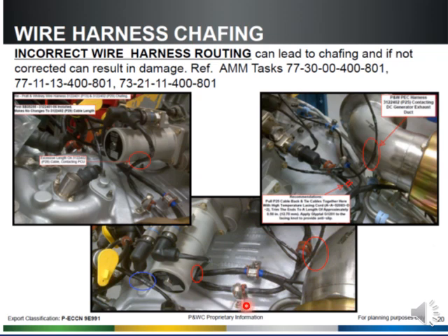Looking at the routing here, you notice that the installer routed the wires so that there's chafing all across the engine. This is somebody with experience routing these wires, and notice how poorly things have been routed. So please be mindful that when you put engines back together and you're doing your engine changes, that the wires are routed appropriately.